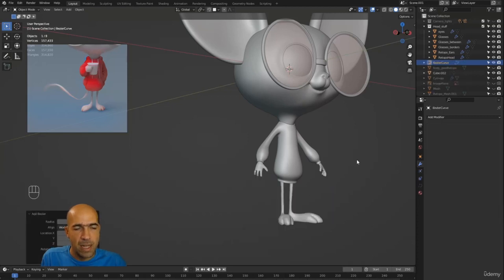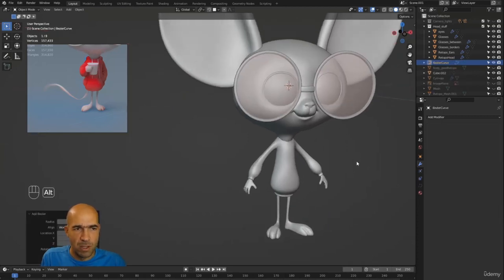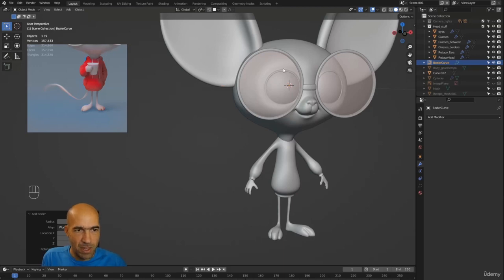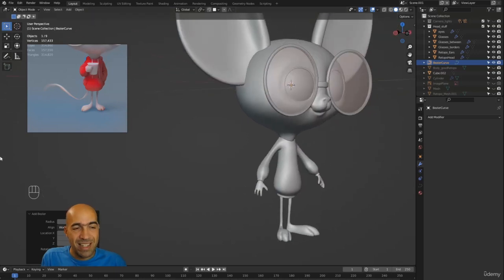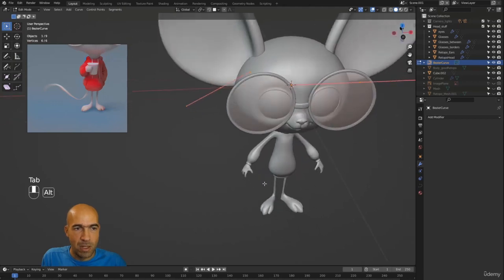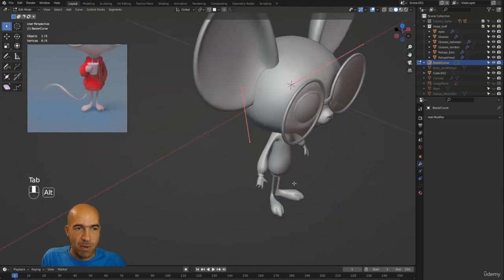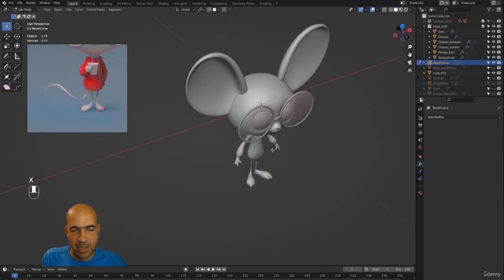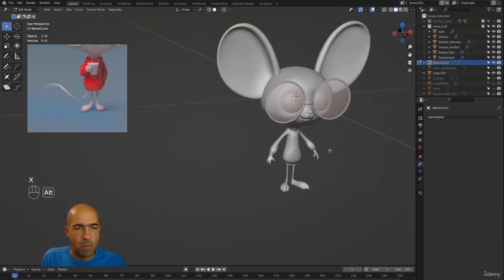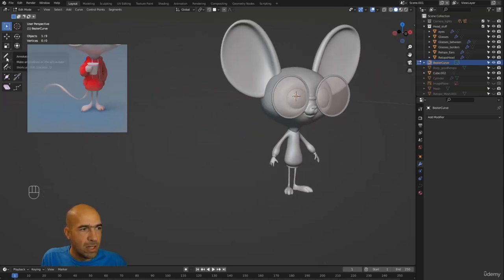So we'll add it. Now, where is it? We don't see it, right? It's around here in the middle because everything appears there, because there is the 3D cursor, this little stuff here. So our curve is there. We'll press immediately Tab to go to edit mode, and we will see some of the handles of our curve. And what we'll do is select it and press X and delete it, basically. Vertices, no problem.